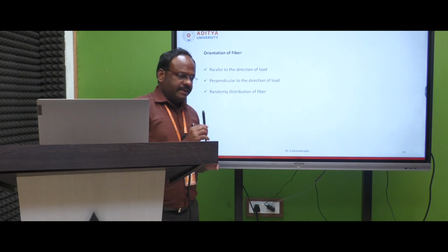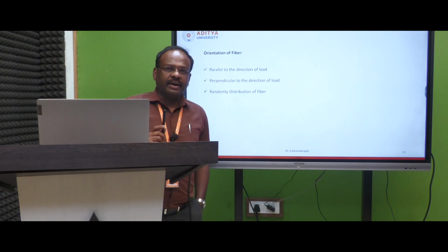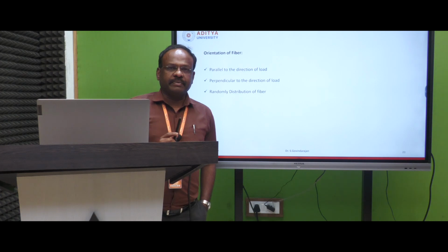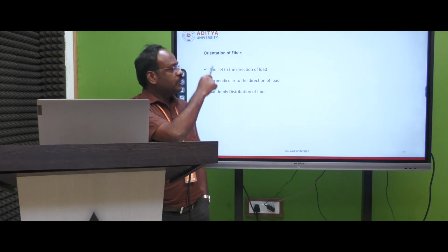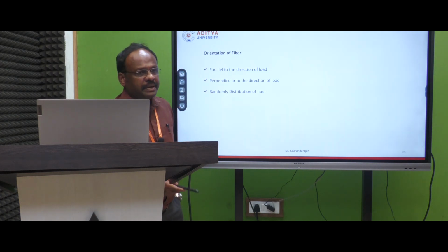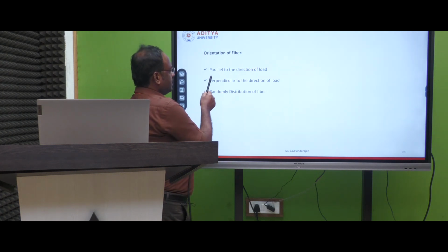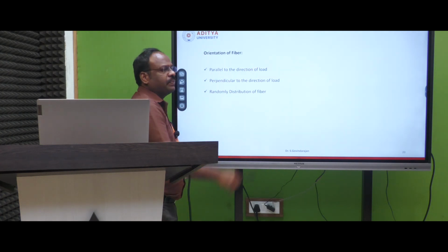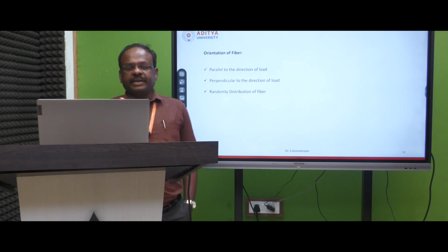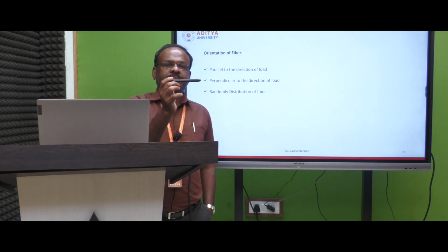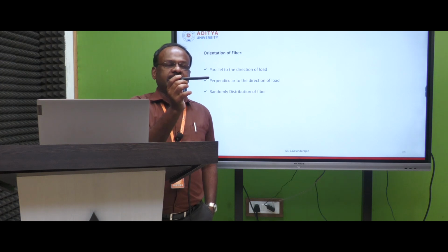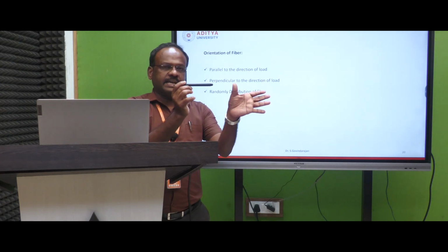Here, which one is suitable for the orientation of fiber, which one is the correct one? According to the three, which one is the correct one? Taking all three, the first one, parallel to the direction of load. Why? Here I place the fiber horizontally, where the load is acting in the horizontal direction.